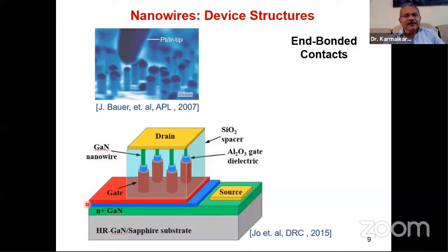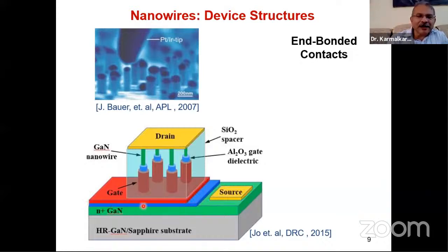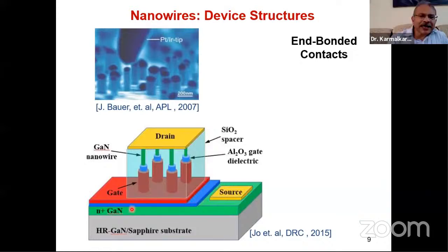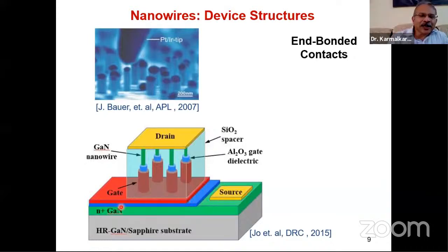It doesn't matter if you make a mistake also. I just want... Is it an insulating material? Yes, you are right. It is an insulating SiO2 layer. Why is it an insulating material? Because the drain or source is not directly connected to the gate. Correct. So the drain and source should not get shorted.